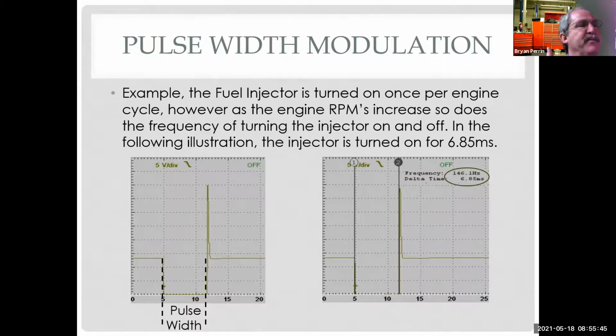So this happens to be a fuel injector right here. Fuel injectors all have inductive kicks. Ignition coils have inductive kicks. The bigger the electromagnetic field, the more likely we're going to see an inductive kick on the pattern. If this right here is my system voltage of 14 volts, we've got like 60 volts here. 12-volt ignition systems will get inductive kicks of over 200 volts.